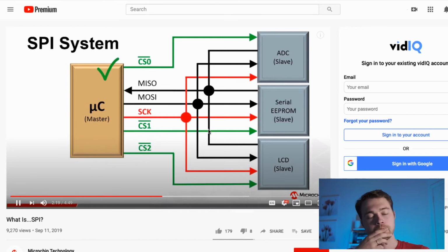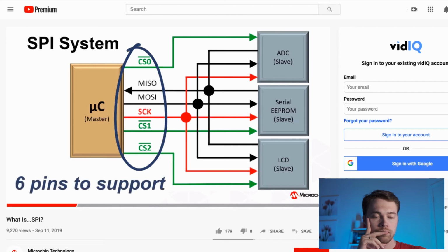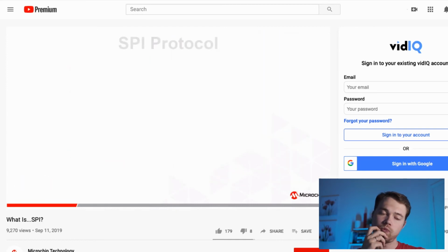The microcontroller is the SPI bus master, and the 3 slaves are an A to D converter, a serial EEPROM, and an LCD. Note that each slave device needs its own CS signal, or I/O port, on the MCU. That is a total of 6 signals versus the 2 signals in a 3-slave I2C system. But remember, we gained throughput speed with SPI.